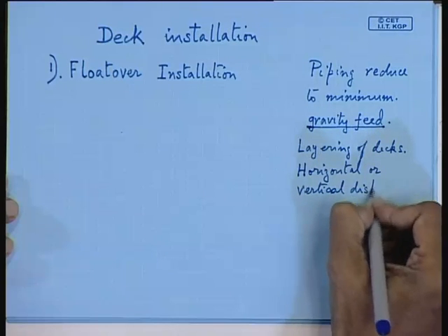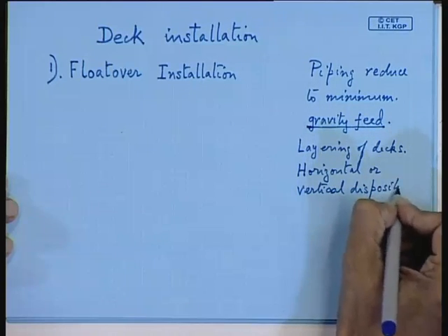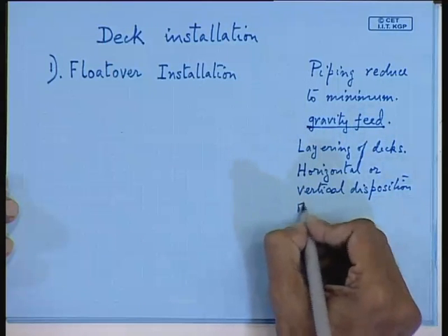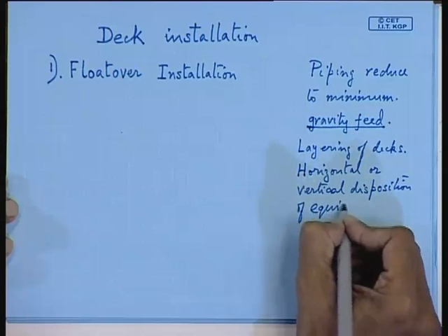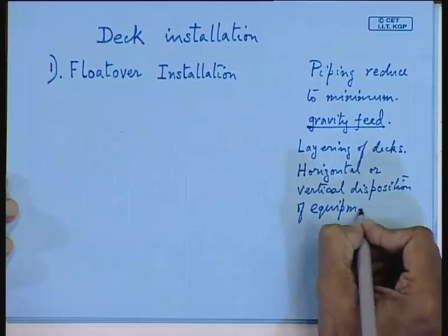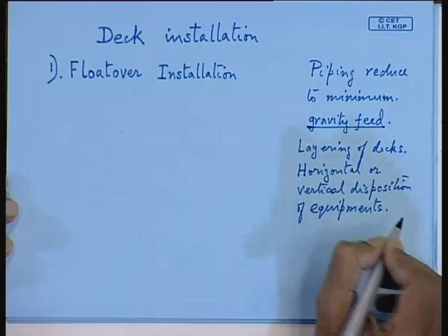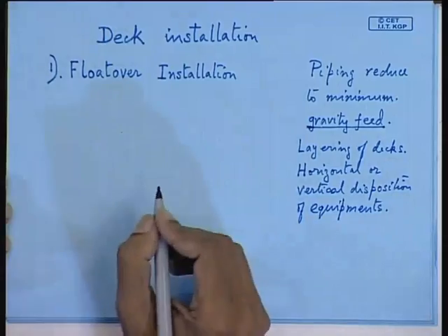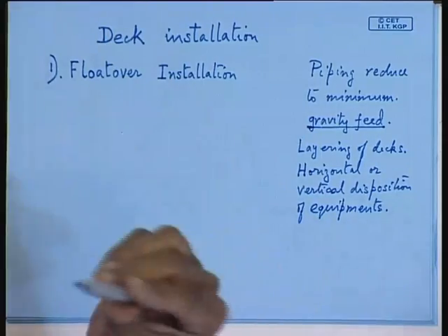Now, these you find out in the disposition of equipments. You will find that some compressors or say heat exchangers can operate vertically instead of horizontally, but if you place them horizontally, you will require a larger amount of deck area, but if you place it vertically, obviously your deck area is less. Now, there are problems that will come up when you have a compressor like this.